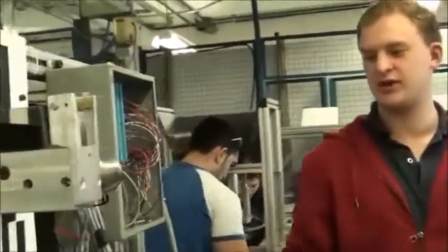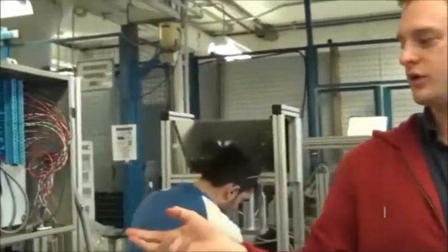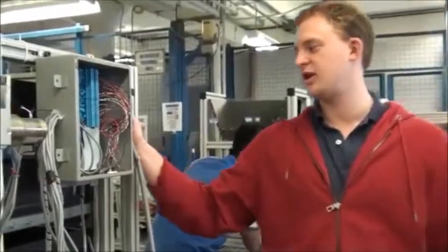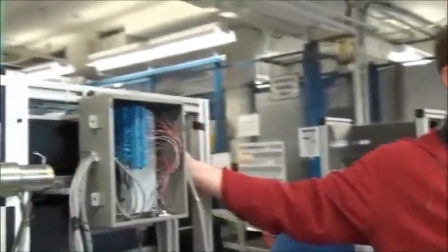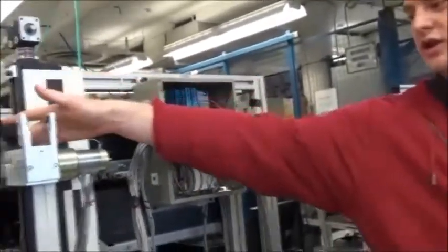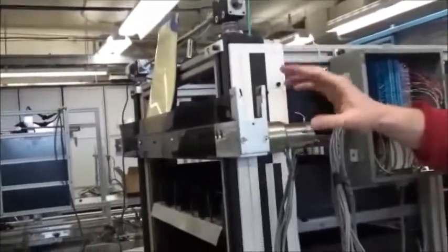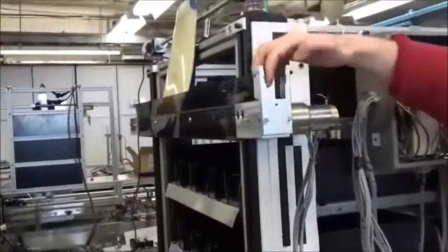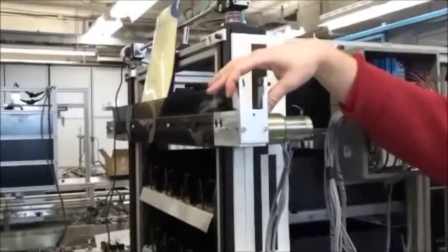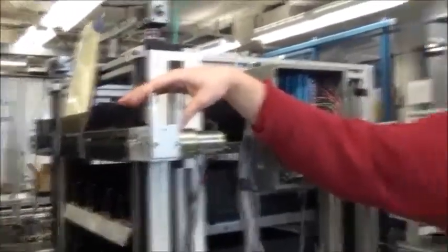Okay, the process is going to work like this. A programmer programs the PLC so that an operator can just click a button and say, okay, I want a block of wood from this motor. When that happens, this motor will activate, bring the block of wood here, and then this motor will activate this conveyor. The block of wood will be placed here. We plan to have a sensor to signal that the block of wood is in there, so that the robo cylinder can come and grab it with the gripper.